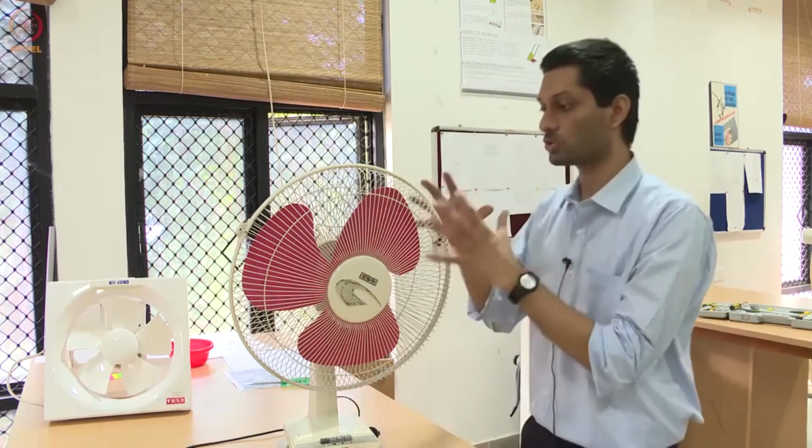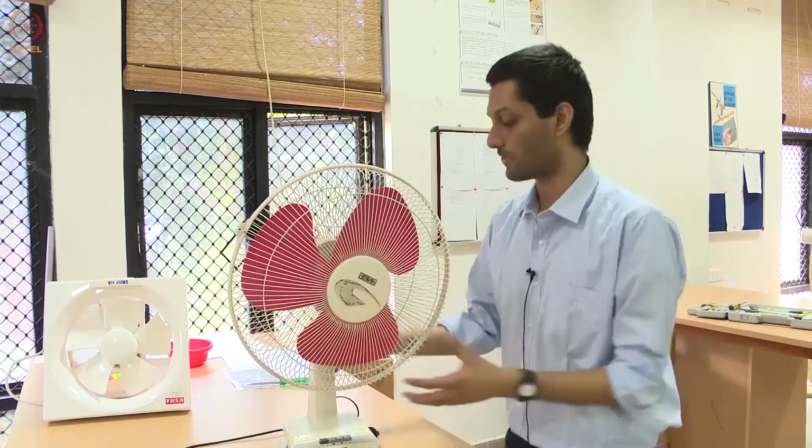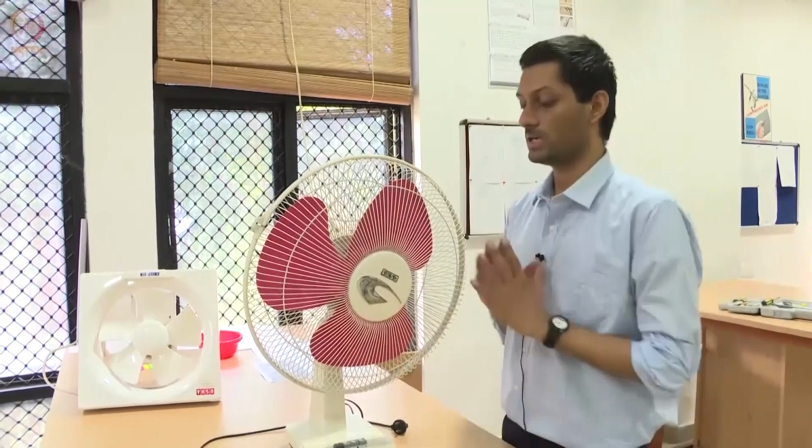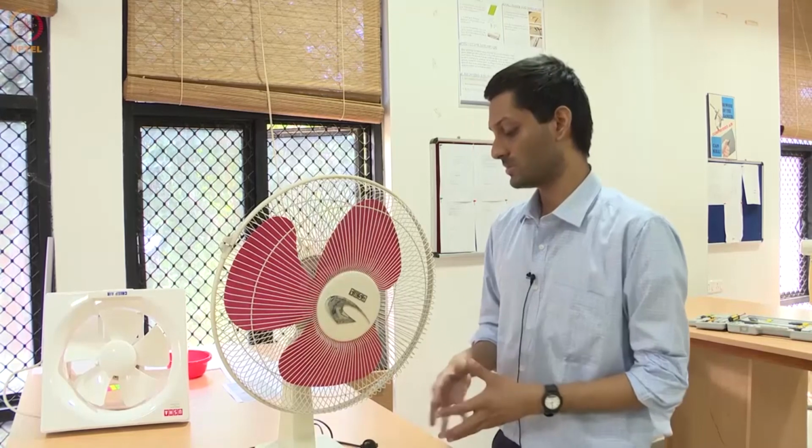So now I'll go through the individual level, and then let us look at the dismantling of the product itself. Beforehand, I've removed all the screws just to speed things up. So now let me remove the guard of the fan. One key thing to keep in mind is that for any consumer device, you should always keep the number of fasteners to a minimum, primarily because the more fasteners you have, the assembly time is going to increase, and also the cost is going to increase. So in many of the connections that we see, we'll make use of snap fits. I'll show you what they are when we talk about the exhaust fan.